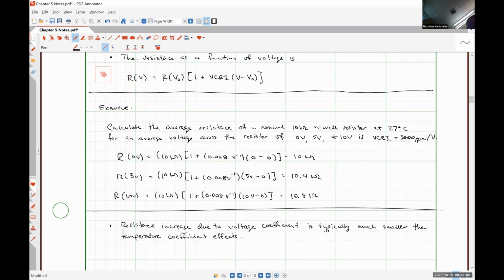All right, so for instance, in the C5 process, the maximum allowable voltage for our devices is going to be 5 volts. That's what the process is designed for. Anything over that would potentially cause the gate oxide region of our transistors to break down, rendering our transistors inoperable, right?